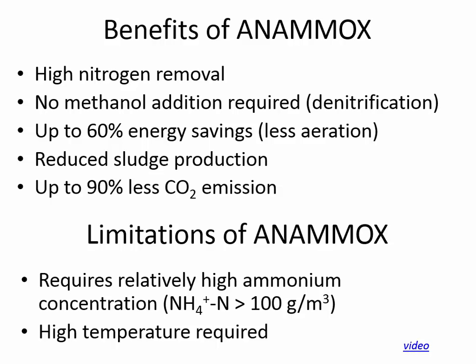Unfortunately, it's not applicable to most wastewater treatment plants, not yet. It's only been commercialized since around 2002, and there are only about 20 of these ANAMMOX reactors in the entire world. Most of them are for food waste, where there's a really high concentration of ammonium.